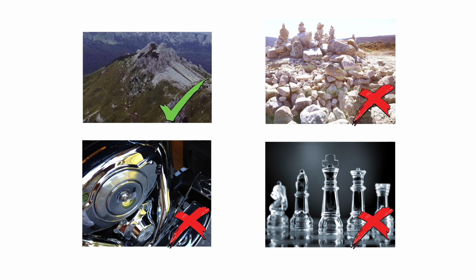Firstly, let's talk about capturing the video. Only certain types of subject can be captured via photogrammetry, and only when lit by diffuse lighting, i.e. no direct sunlight. So when capturing things outdoors, capture them on overcast days, and if you're indoors, don't have any powerful direct lighting like spotlights. Also, you can't capture anything transparent or reflective, as this confuses the algorithms used by the software.